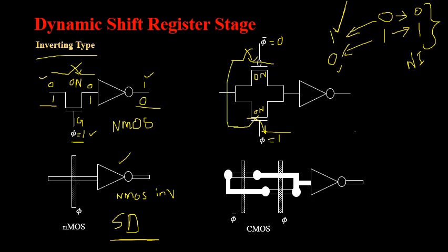There is a parallel connection from your PMOSFET to the NMOSFET. So it can take any one of the paths. If I apply a logical 0 as an input, either it can traverse through here or through this path. Since it is equal to 0, it obviously takes the path through the NMOSFET so that it can yield exact logical 0 state.